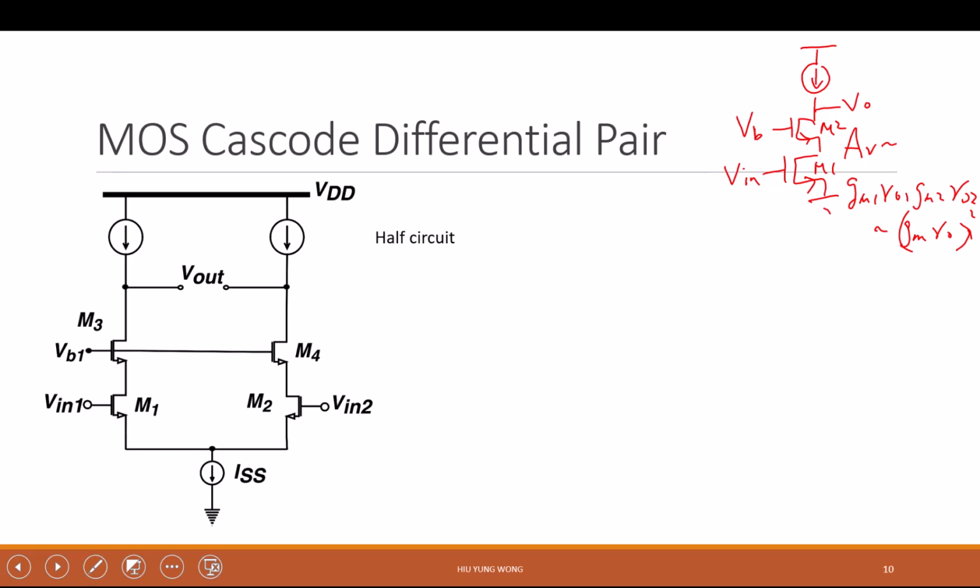Okay, so let's come back to this circuit. Again, this is easy to find out if this is symmetric. I just cut it here. And yeah, M3 equal to M4. It is given. M1 equal to M2 given. So it's symmetric, right? So I'm going to put a virtual ground here. Virtual ground here. I'm still going to remove this, right?